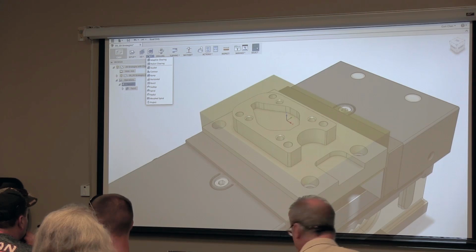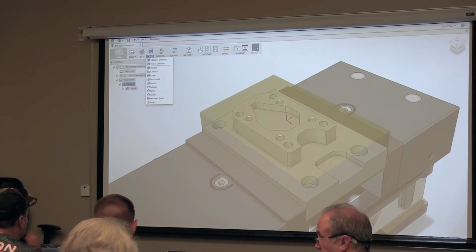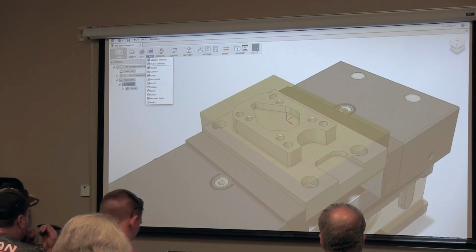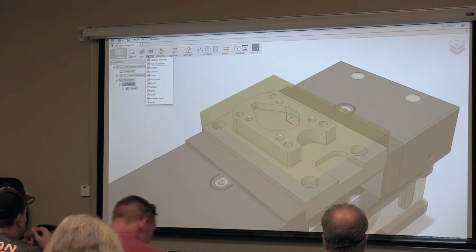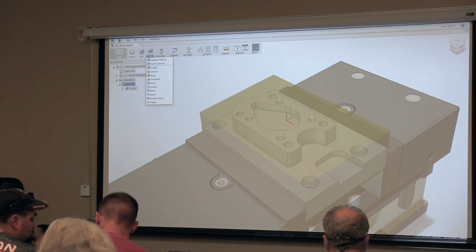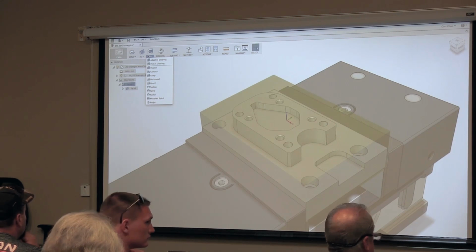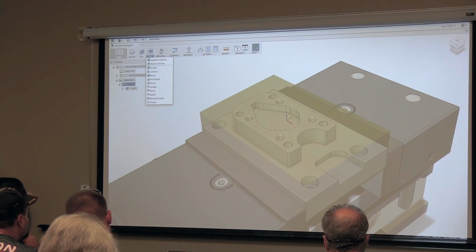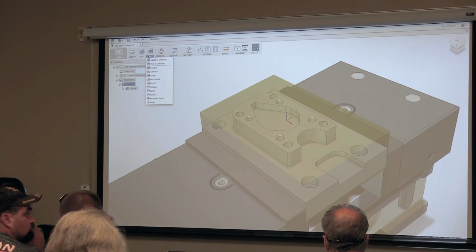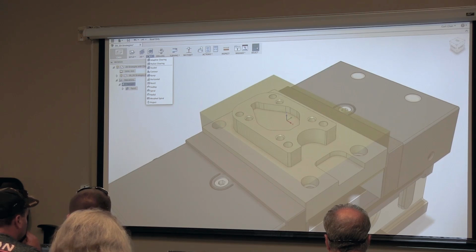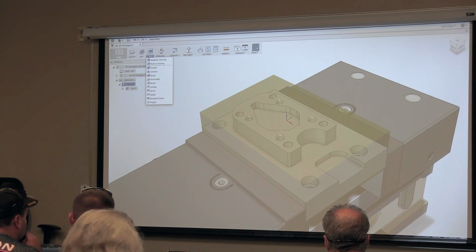To face the part, let's delete this and do it again. Go and delete that guy and let's go up to face. 2D Face. Yep. The tool is, go and click that. Mirror. Yep. And now just say OK. Hit OK. That's it. There you go. The whole face, so that's why, because you picked the surface. If you pick a surface, it's only going to look at that surface. The nice thing with the face profile, it knows exactly what to machine. There you go.